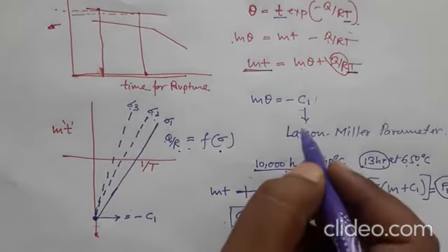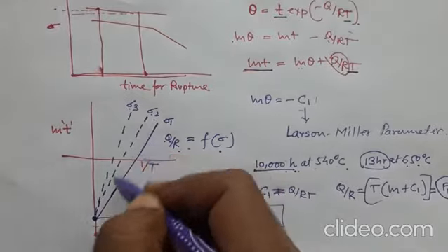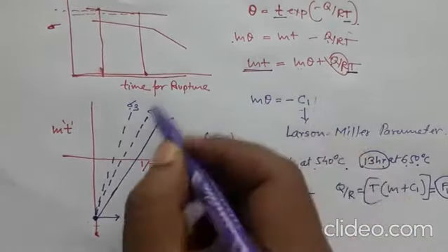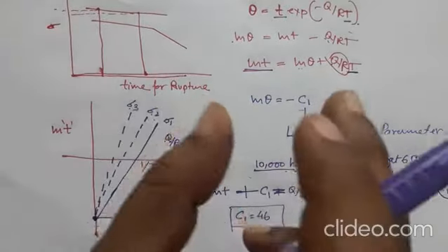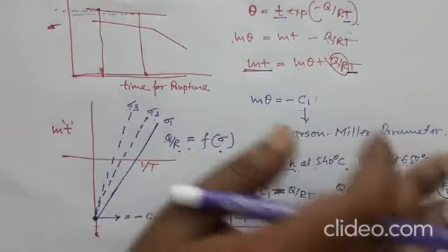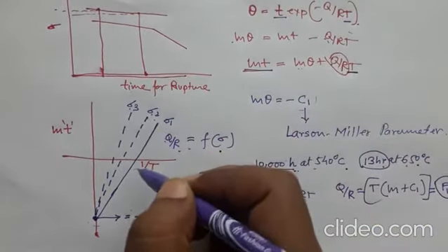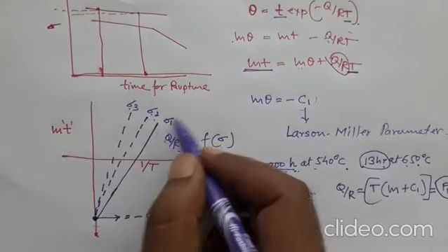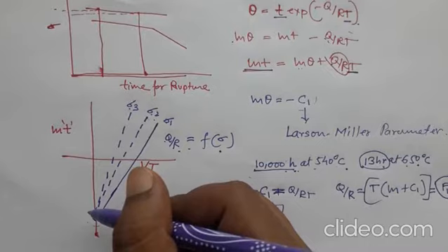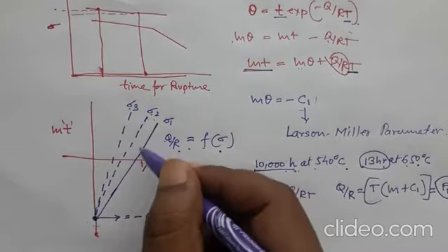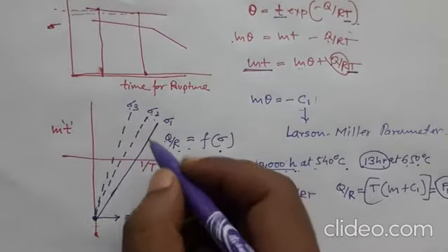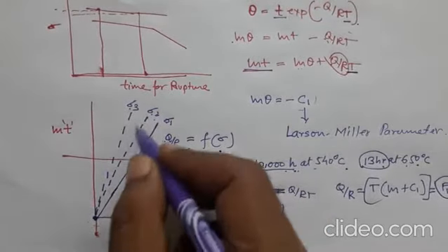Okay? So here the intercept, so all these lines, if you do the testing at different stress values and you put the specimen under the load, under constant stress, and let it fail, and then you plot the temperature versus the rupture time at constant stress, you get a straight line like these. Okay? So you do it at obviously different temperatures, and that's how you get this straight line. So you do many tests at different temperatures until failure, and you draw these lines.